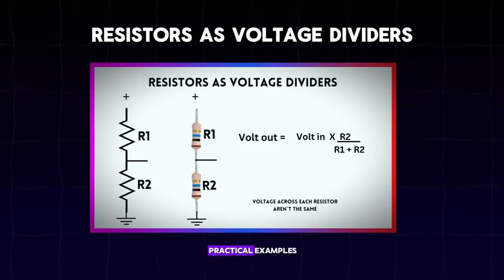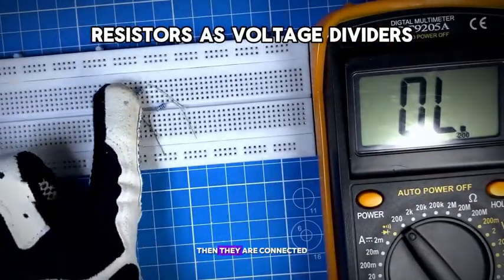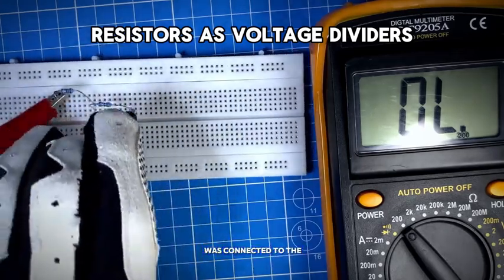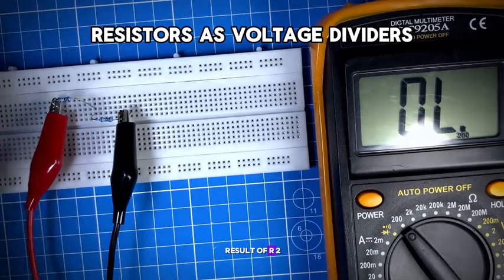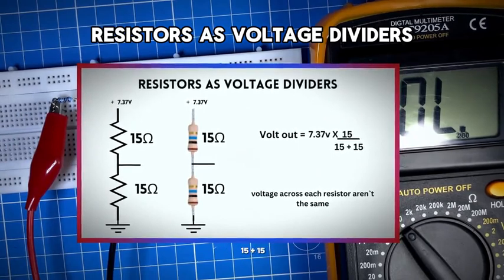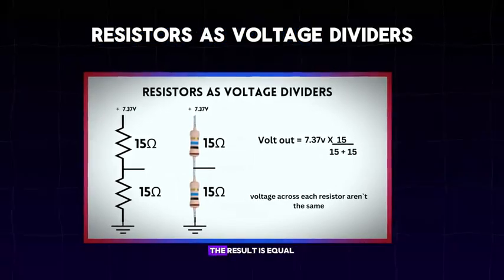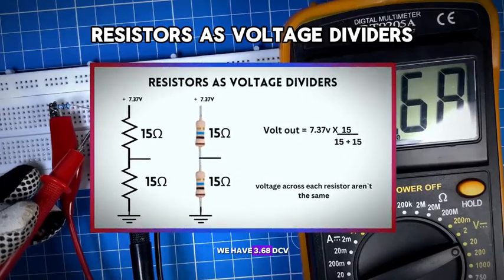So let's use a practical example to see how voltage dividers work. These resistors are 15 ohms each. They are connected in series, and 7.37 volts DC was connected. The negative probe was connected to one end, and the positive probe was connected to the other end. To find Vout, multiply 7.37 by the result of R2 divided by R1 plus R2, which is 15 divided by 15 plus 15. So 15 divided by 30 is 0.5. Then 7.37 multiplied by 0.5 gives 3.68 VDC. As you can see on the multimeter, we have 3.68 DC volts.